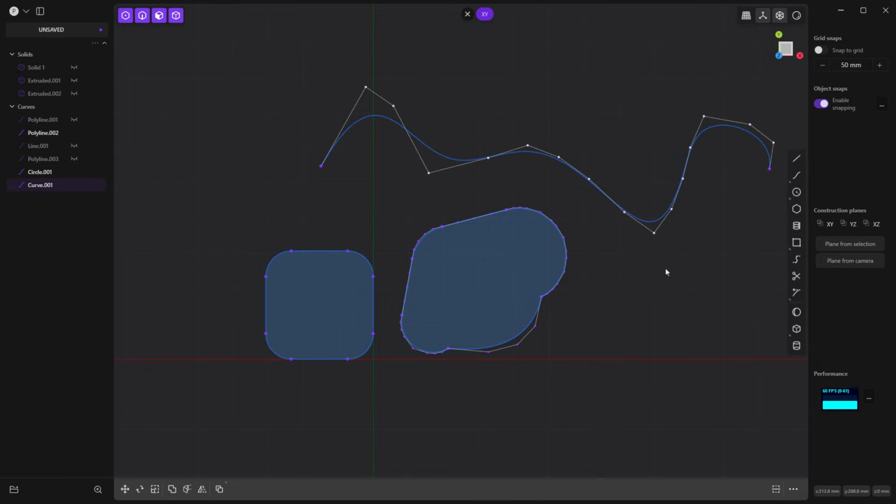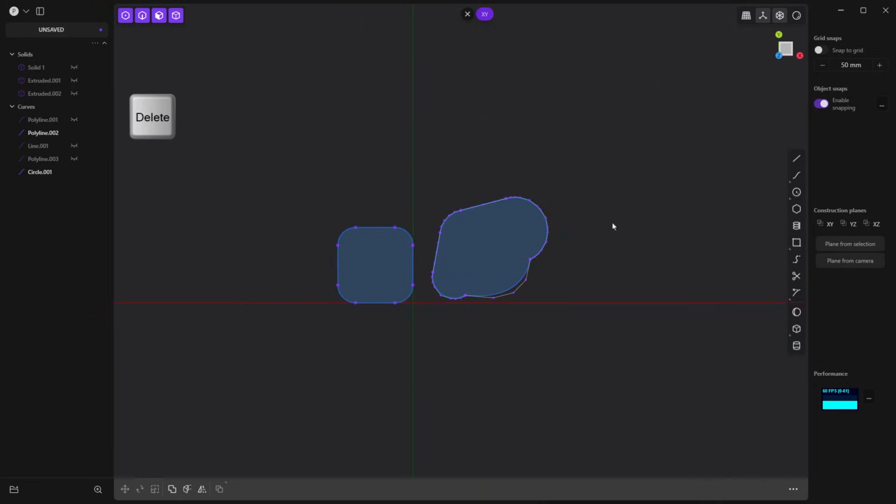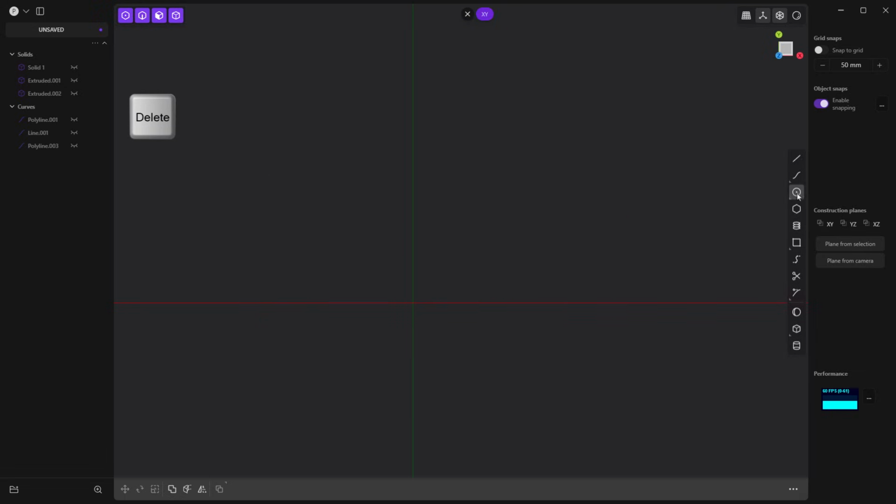Using raise degree in this case is only going to add to the control points, which makes control a little bit harder. So it's probably going to be a less practical case. Most of the time you use raise degree on a sheet or a surface, but it does have its place in some cases on curves like this. So I don't really need this curve, but let's go ahead and delete that. And let's talk about maybe one more thing that I think is important that we mention. I'm going to go ahead and delete both of these actually.